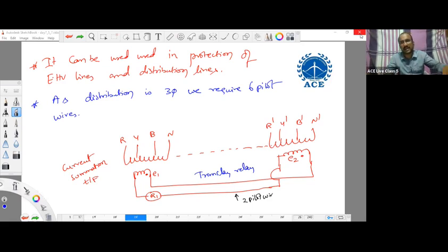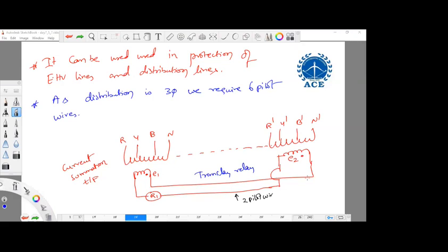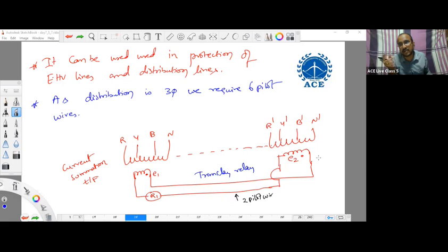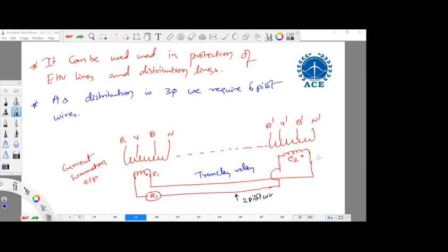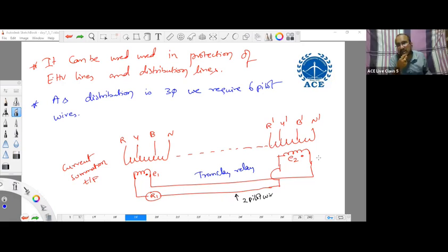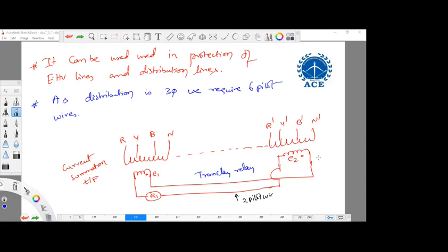Actually, the voltage regulation previously allowed was 10%. So if you want to get 100 volts at the end point, you should operate at 110 volts at the sending end. That's why they have gone for that. But now there is no standard for using that; sometimes they are violating it also. Sir, I'm asking why we use these specific numbers, 11 kV or 33 kV or 66 kV.